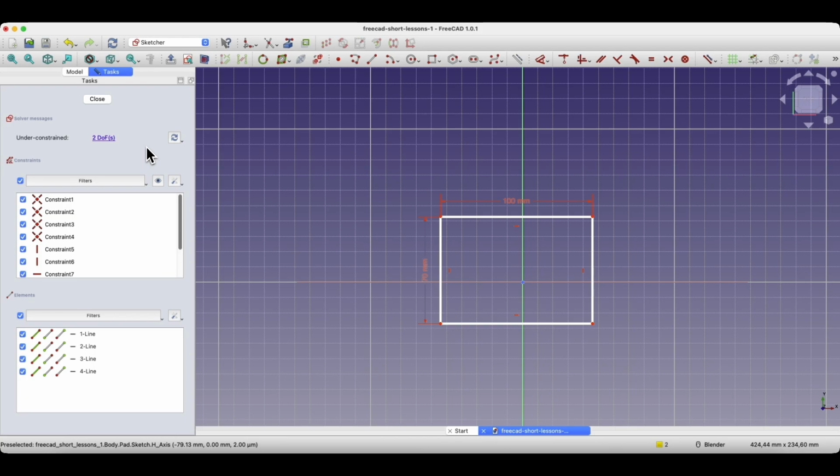We create a sketch, add a solid operation, then create another sketch, add another operation, and so on. If, for example, the sketch in the early stages is not fully constrained, and we accidentally change the shape or position of such a sketch, it may affect subsequent stages of the project, and the entire project may simply be damaged. Therefore, let's strive from the beginning of learning the basics to aim at removing all degrees of freedom.